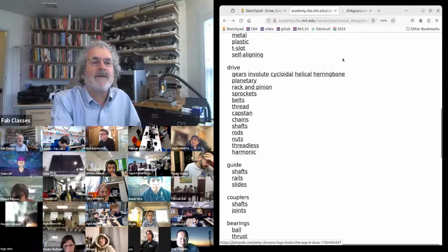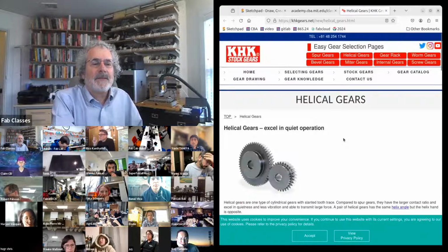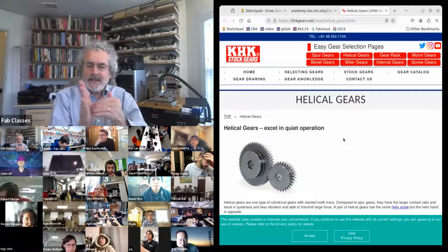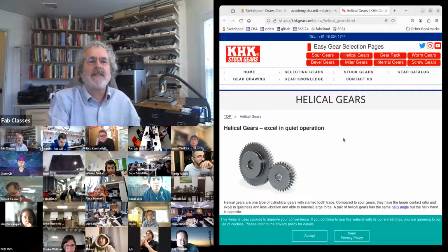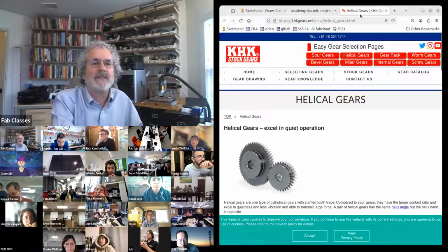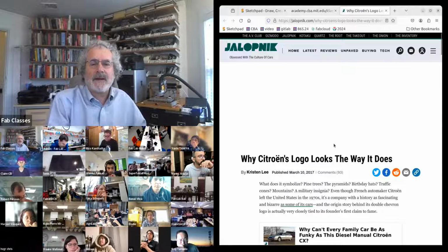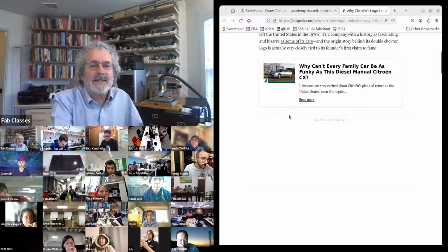So then there are many other interesting gears. Helical gears are continuous. In addition to the rolling being continuous, the teeth engage more continuously. And then herringbone gears do that in 2 axes.